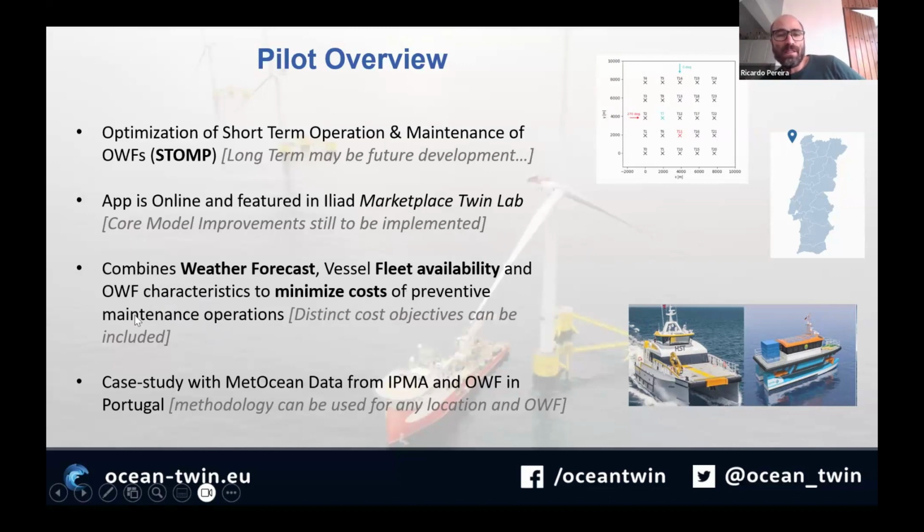What this means is that, especially according to the wind directions, as you will see in a little bit, you might want to change the sequence of operations, because there are aerodynamic interactions between the turbines, namely what we call wake effects. Generally speaking, you want to make the interventions on turbines such that you minimize the energy loss. In other words, we try to minimize the costs, because you minimize the energy loss, and so you also minimize the costs of your maintenance operations.